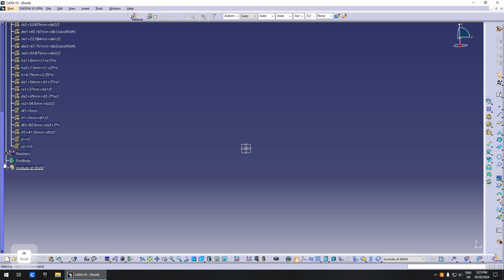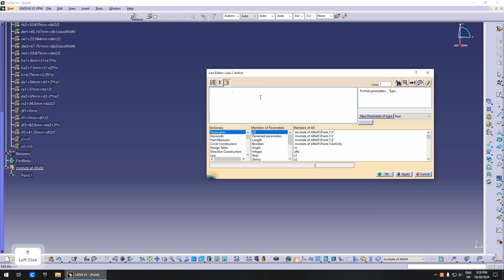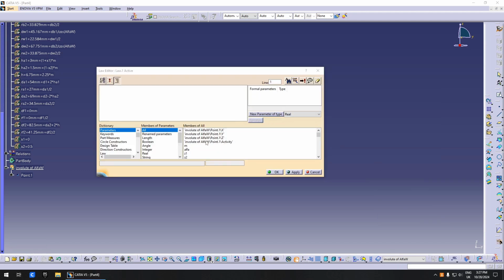First, we'll have the 0, 0 point. So in order to calculate this, you need the involute function. So this you can create a law here. You see under this table. Click OK. You know the involute function equals tangent of an angle minus the angle itself. And transposing that into the formula editor, it looks something like this. So you have the tangent from an angle minus the angle itself, and this is just to transform it to radians.